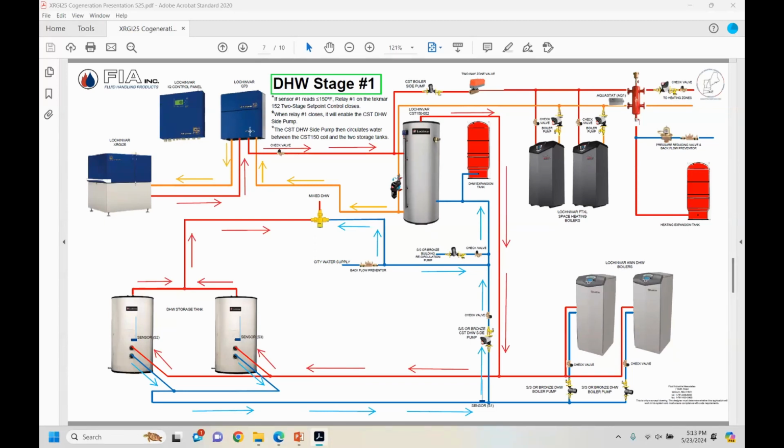So there's a heat exchanger in here with a circulator that's circulating between these two circuits. That's really just isolating, keeping this circuit nice and clean, while this may be influenced by system water and debris. And so all the cogen really knows is, hey, this tank is hot, or it's half hot, or now it's three-quarters hot, or the whole thing is hot. And so let's say it's cool, it kicks on, the unit heats up, we dump water into here. So that's all the cogen knows. From there, there's a couple of ways we can use the heat.